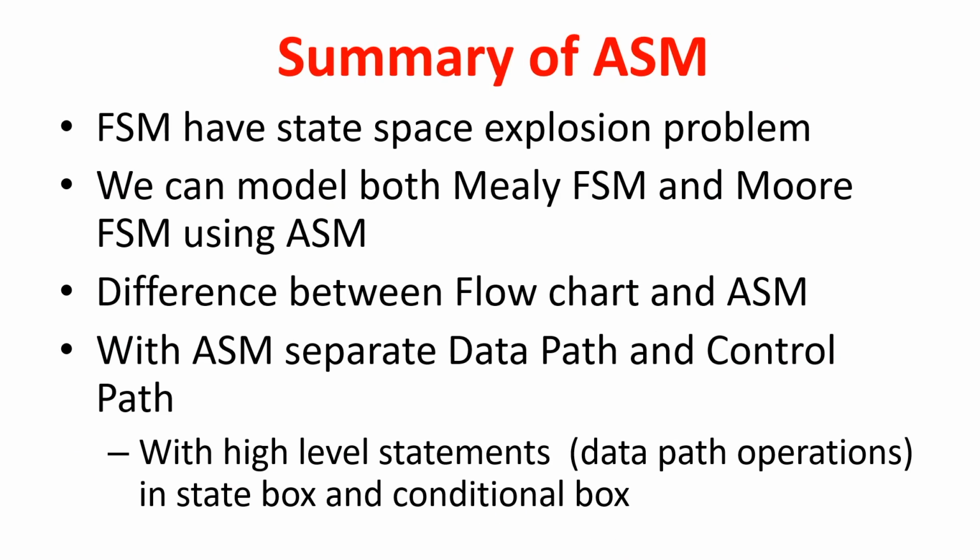And what is the summary of ASM? FSM has the state space explosion problem. We can model both Mealy FSM and Moore FSM using ASM. The difference between flowchart and ASM is that a flowchart does not have timing information, while ASM has timing information.